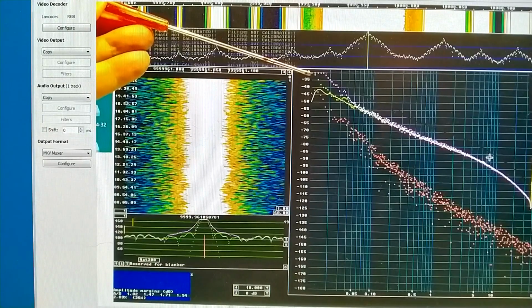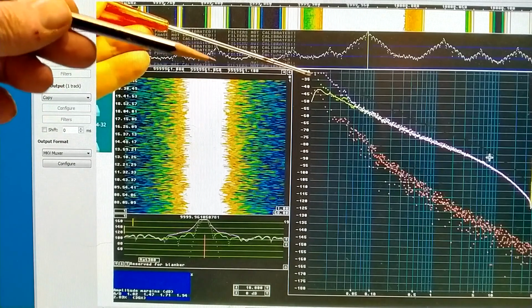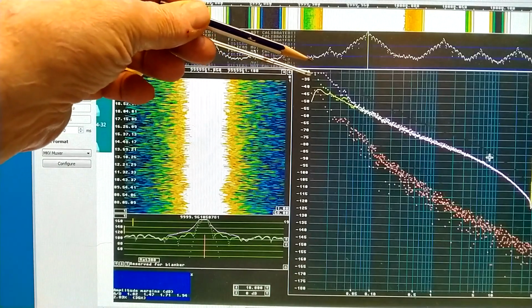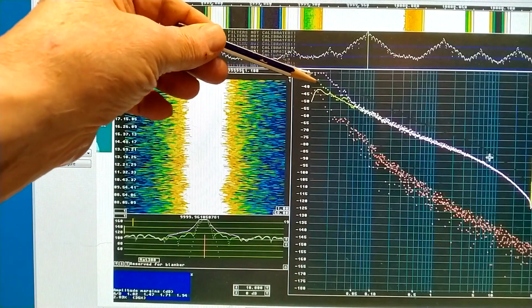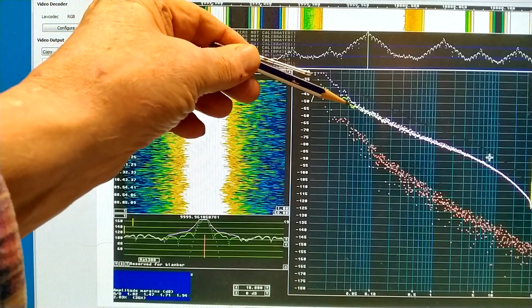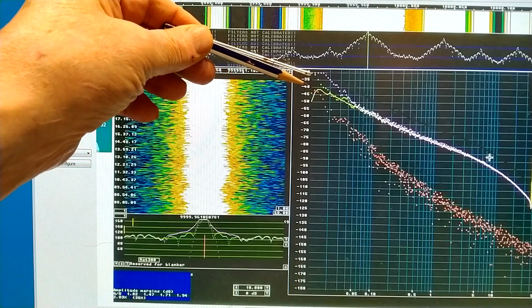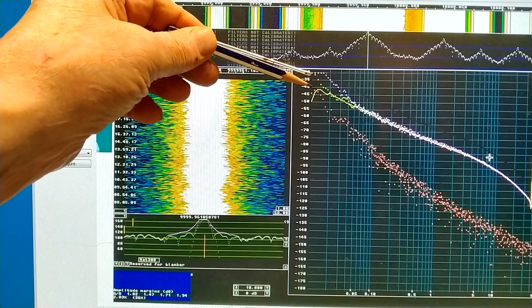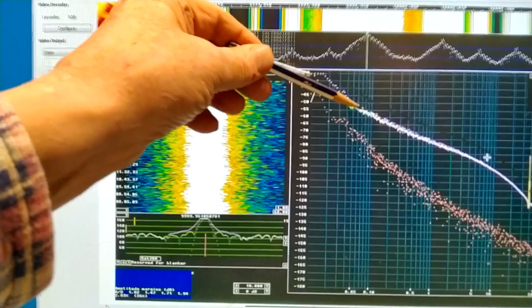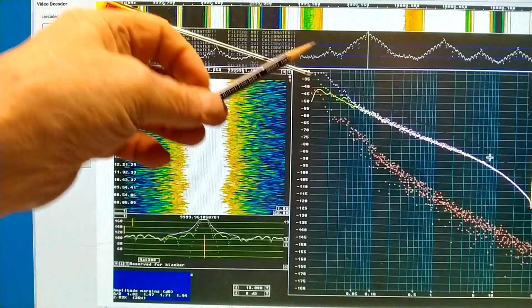Here is the phase noise spectrum of the rubidium stabilized oscillator, the LPRO 101 from Efratom. It is clear that it is much better than the two reference oscillators in my system, channel 2 and channel 1, because it's the yellow, the correlated track, that is the rubidium oscillator. Down here, statistics is too bad, but I can assume that this is a straight line, and that means that